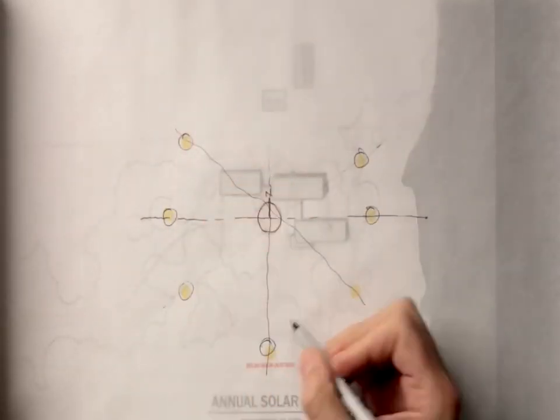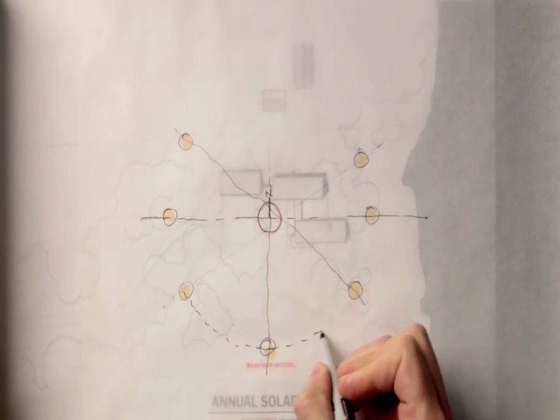The predominant solar orientation, where the most direct sunlight comes from, here in the Northern Hemisphere, is the south. So the more of our building that can face south, the more efficiently we're able to capture and use the sun for natural light and passive heating, and even cooling, as we'll see in a minute. This approach not only saves energy, reducing lighting, heating, and cooling costs, but it's also better for our own health and well-being.